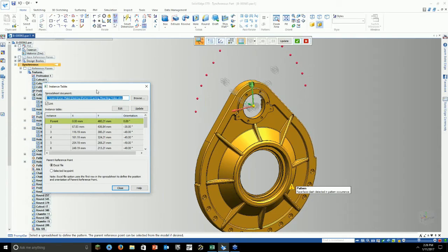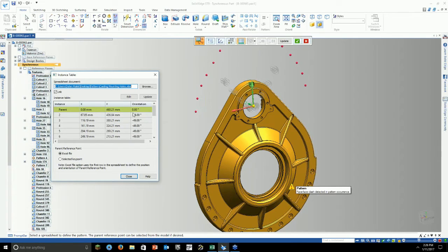But let's take a look at this field over here real quick. Again, this kind of looks like an Excel table, which it basically is pulling information from. Let's go ahead and do something. Unchecking that link will mean this Excel will get embedded into this file. That way, you can just use that file as a dummy template and make other items from it. If you leave it linked and you change that table, it's going to change everything linked to it. So it's best to uncheck it and have Excel embed itself into this actual file.